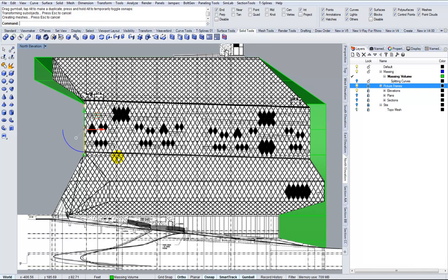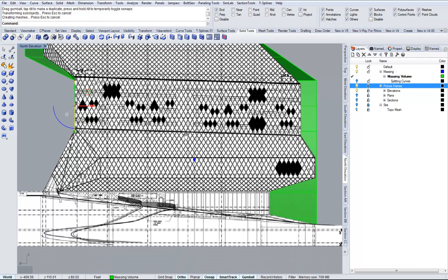That part is actually pretty simple to do once you've got the correct faces. It's more important just to have the correct faces and connections, because after that you can move it and snap it to whatever you need to, and you're kind of guaranteed that everything will stay planar if you use the gumball. So I've moved this in. Now I've got this angle here that I can use. I'm still going to do the same thing.